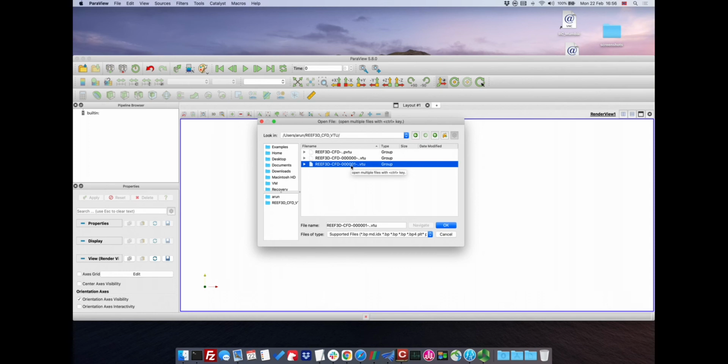So I'm not going to make a video, but just show you how this is working. If I click this arrow here, there are 4 parts. So this simulation was run with 4 processors, that is M10-4. And that's all combined into one VTU that belongs to that particular time step. The same thing here for the second time step, there are results from the 4 processors. All these files here are combined in the PVTU file. So you generally just need to open the top PVTU, the combination of all PVTUs.